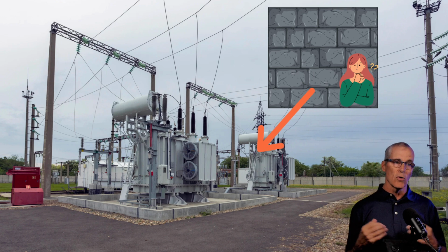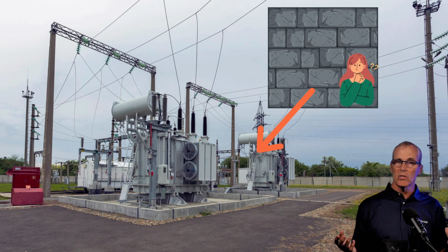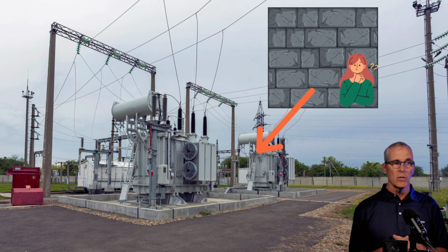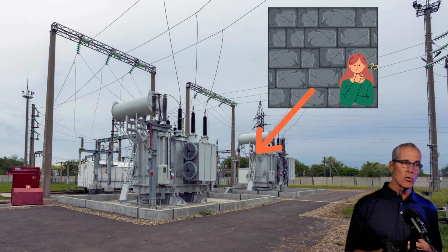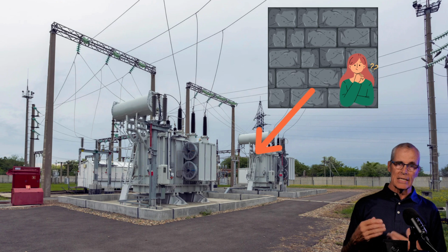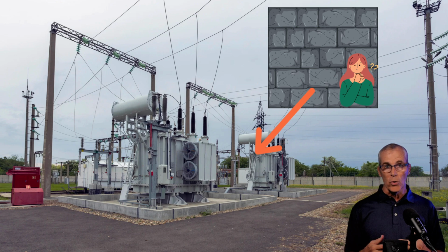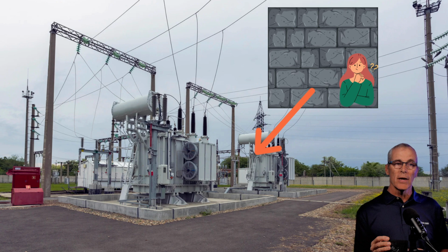What about this? You've got two transformers, two maybe 60% capacity transformers, so you have some built-in reliability, but do you? If one of these transformers fails, is that separation distance that you have adequate? You might have built it in accordance with the code, but let's do some analysis and find out just how safe we are.